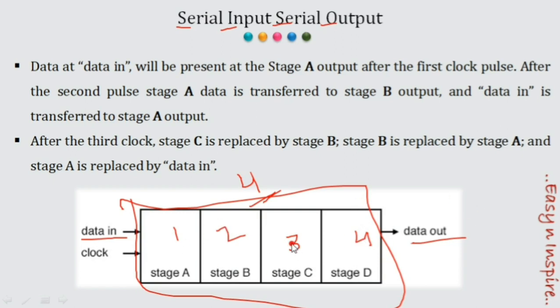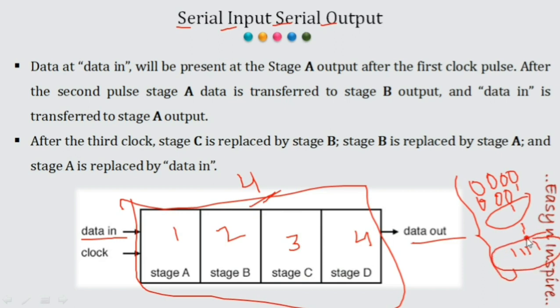So it is used to store data like 0000, or 0001, and so on up to 1111. You can store whatever data you want in this register because it is only a 4-bit register. Okay. So now, in this session, I'll show how to store 4 ones in this register.